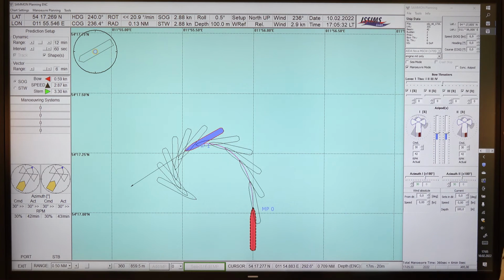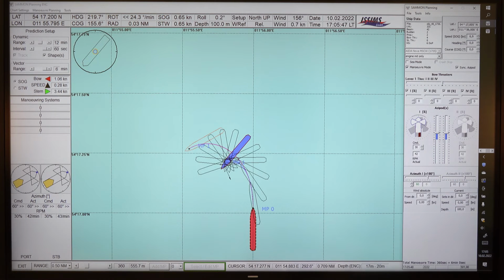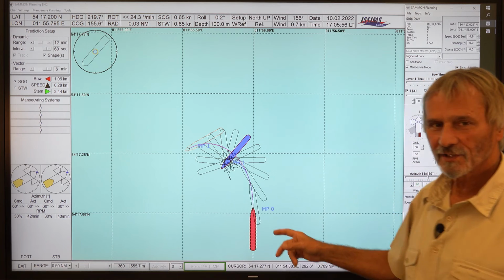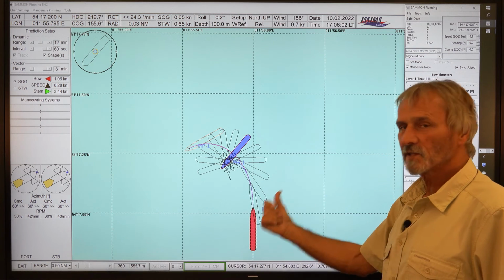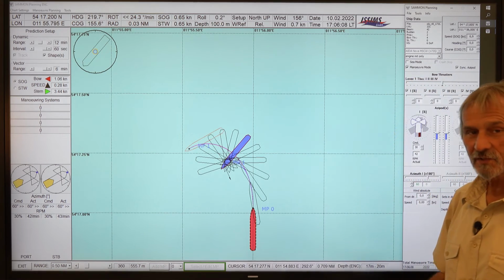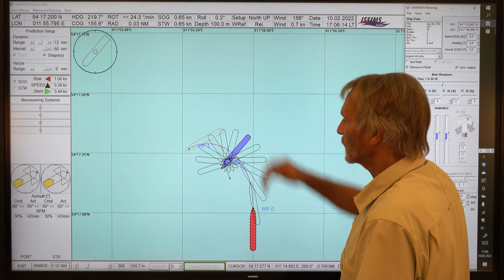Okay, now we can try out some other configurations. For instance, if we go with both pots to 60 degrees, we can even synchronize the pots, and we see they are both working in the same way. So this is now the situation we have nearly seen also when the ship was stopped at the start. The ship is turning heavily, and the transverse forces of the pots are turning the ship finally on the spot. So that's what we have also seen. But as I said, the turning circle is a little bit moved in this direction.